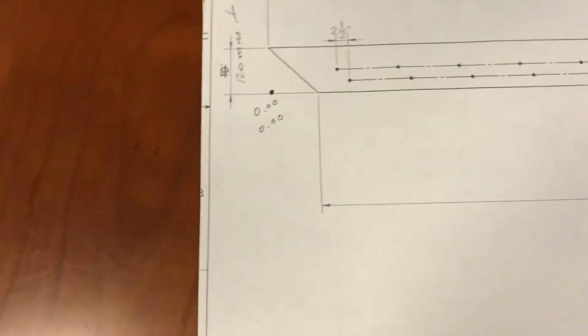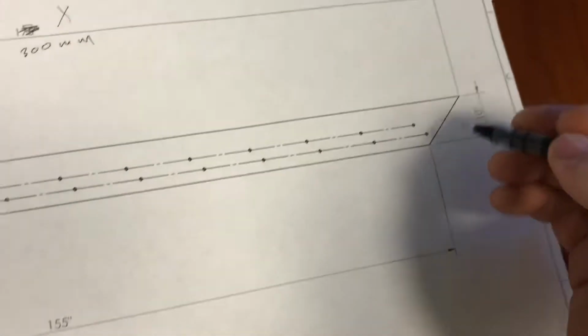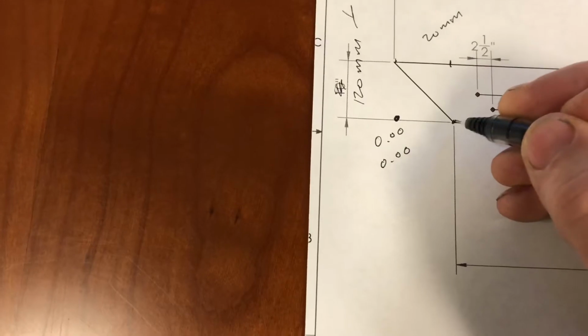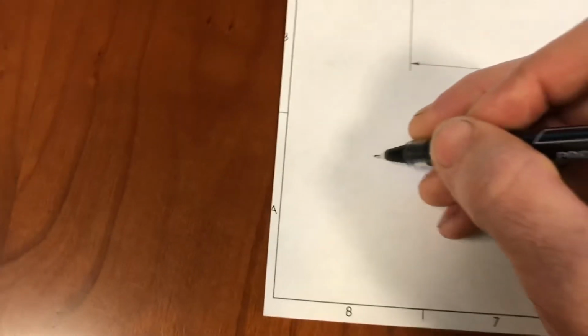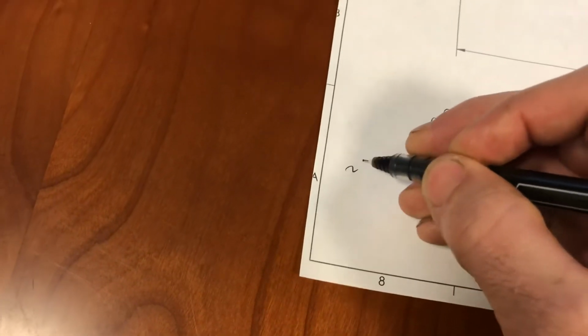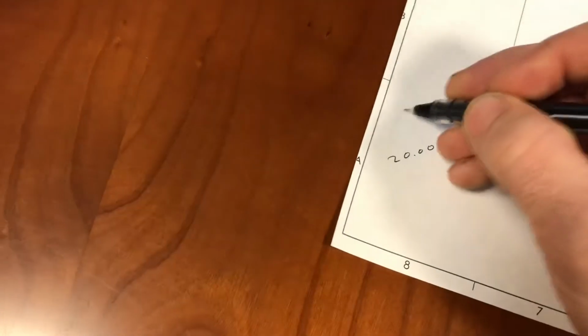So in the descriptor, the first point sometimes starts at one of the corners. So it always starts in one of the corners. Let's say it's here, and let's say this distance from here to here is 20 millimeters. So if your first point is here in the file, you would have 0.00 in Y, and you would have 20.00 in X. And those are the first two columns, the X values and the Y values.